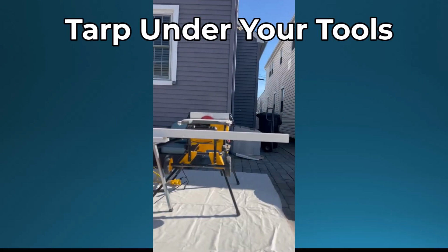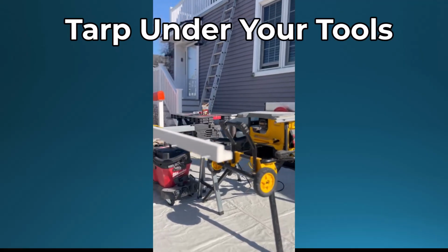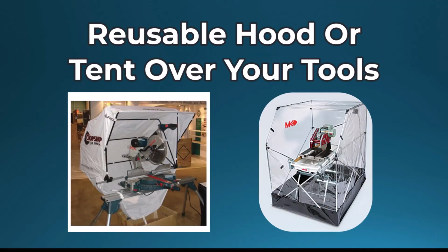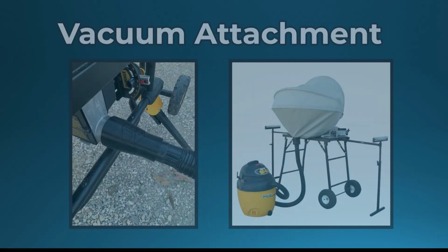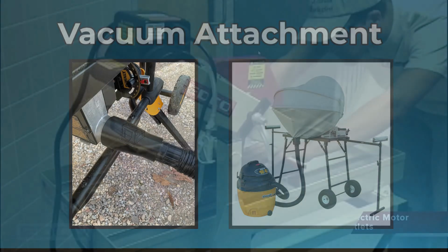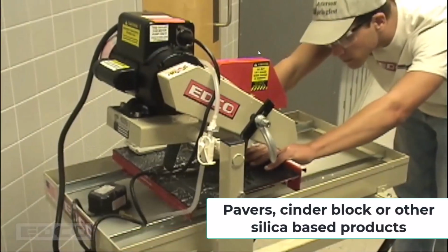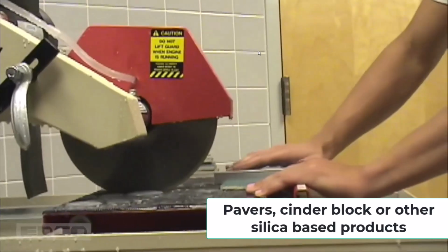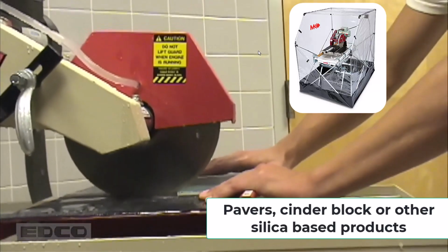When setting up for the day, the first thing you should do is put a tarp underneath your tool and a reusable hood device or tent over it to contain the contaminants from becoming airborne. The tarp also keeps the pollutants from getting into the soil below. Many saws have a vacuum attachment connection that can be utilized directly onto the saw, or the hood that you are using should have a vacuum attachment port to contain the pollutants. If you are cutting pavers or other silica-based building materials, you should utilize water for the saw and also put a pop-up tent over your tool.